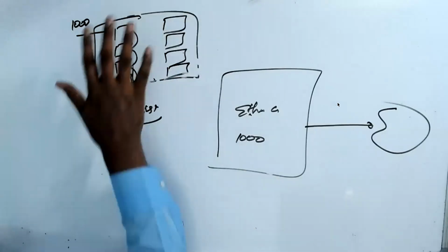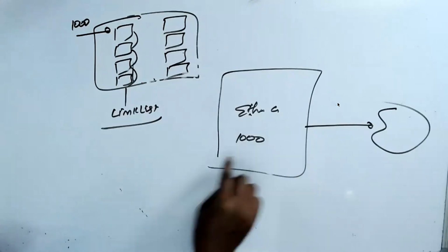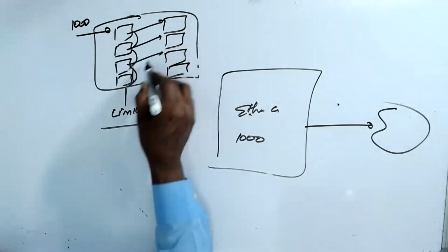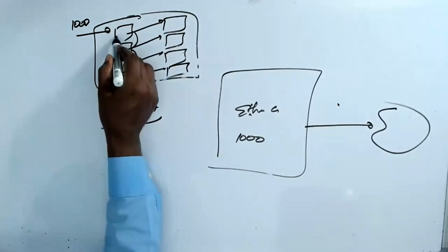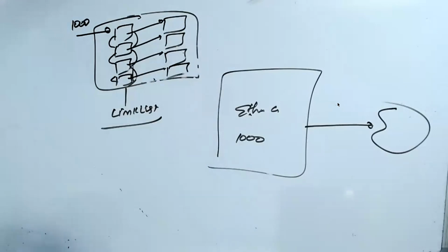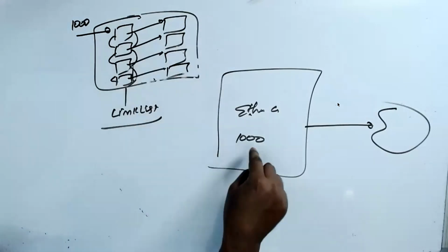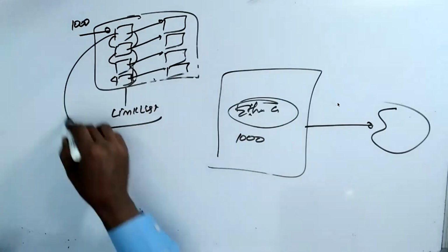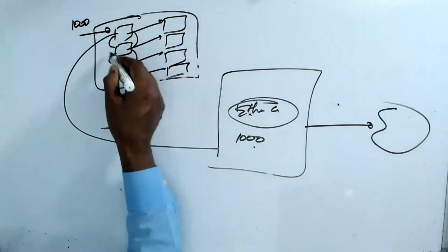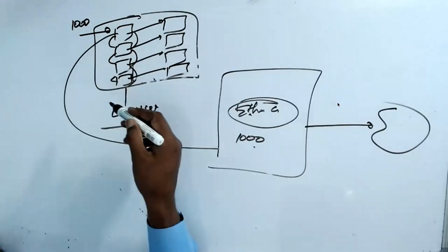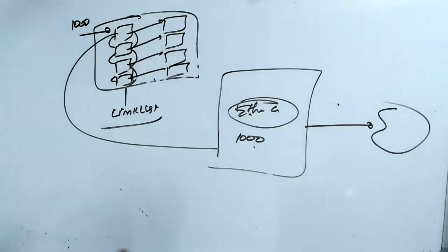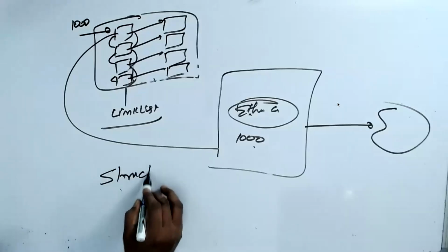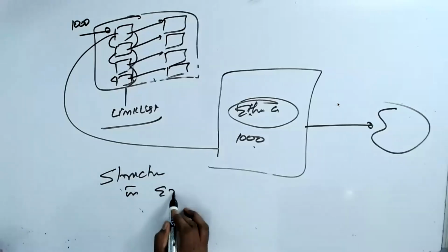You do not have to program this guy, because this guy knows this address. This structure has the addresses, and this guy knows what is the next. So everything is self-contained. You have to tell the Ethernet controller only 1000. This guy will read this and find out what is the next address. He will automatically take it. He will do everything. That is a major advantage of structures in embedded system programming.